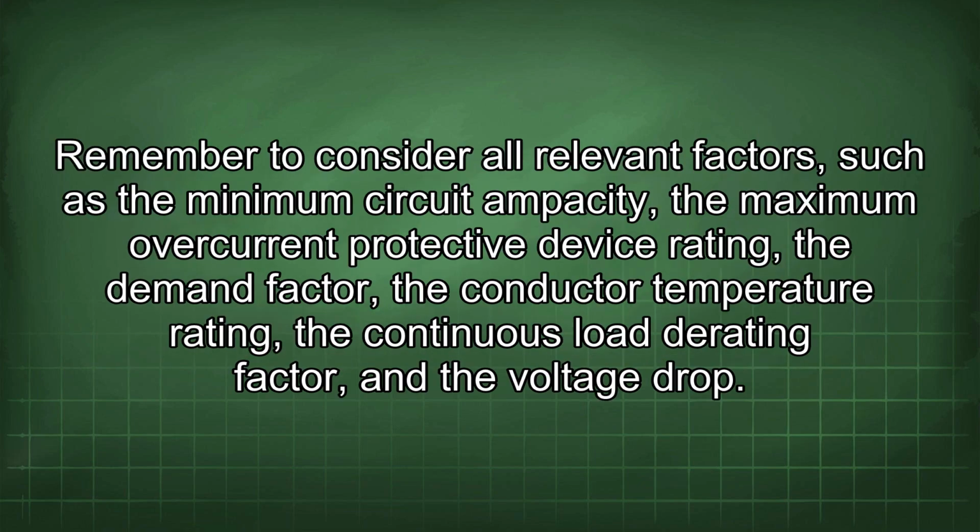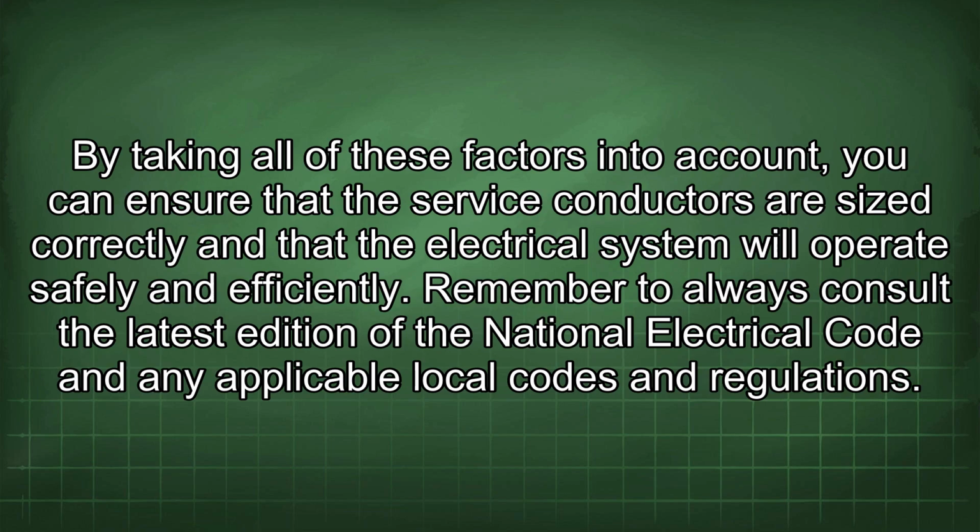Remember to consider all relevant factors, such as the minimum circuit ampacity, the maximum overcurrent protective device rating, the demand factor, the conductor temperature rating, the continuous load rating factor, and the voltage drop. By taking all of these factors into account, you can ensure that the service conductors are sized correctly and that the electrical system will operate safely and efficiently.